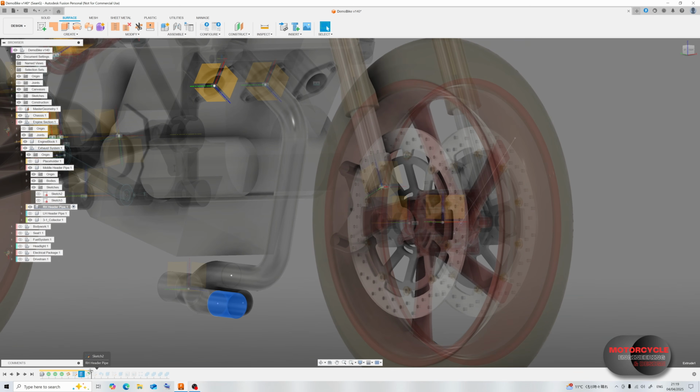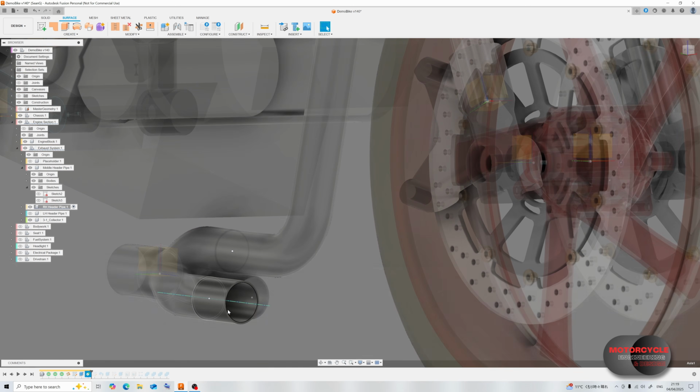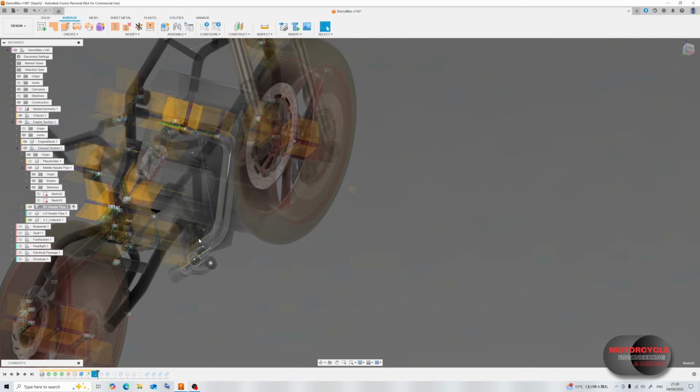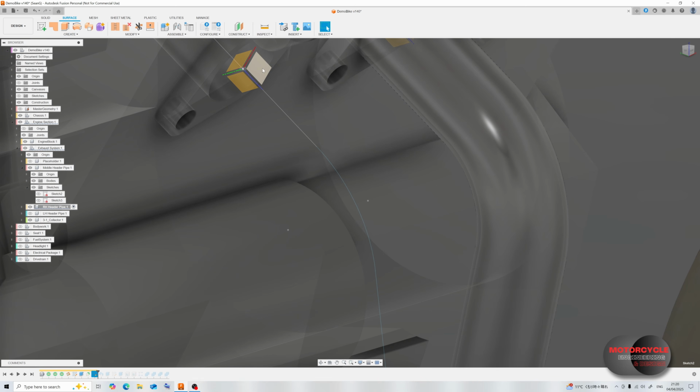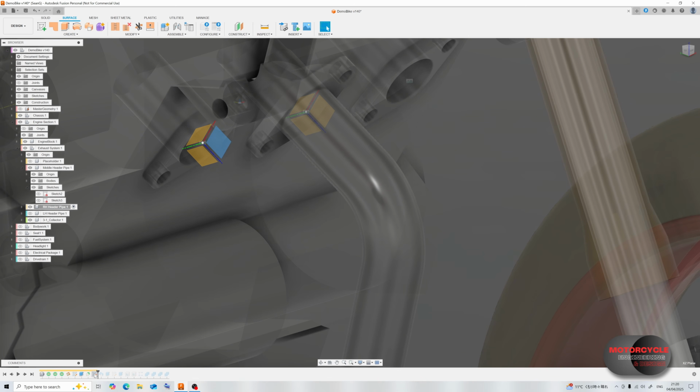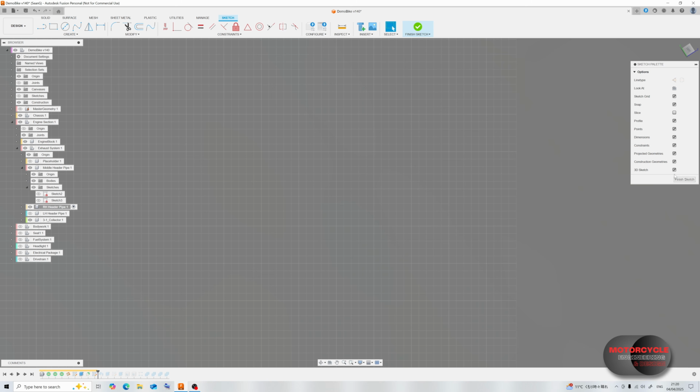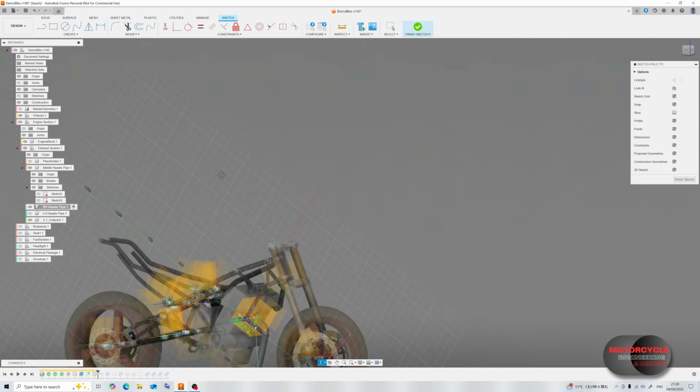The thing I did here was to put my axis here on this new tube that we've created, and then we have a sketch which I create on the main datum, but in this case we go to 3D sketch. Within that sketch, on the sketch palette on the right here, we have the 3D sketch. And I've ticked that so that we can work in 3 dimensions.